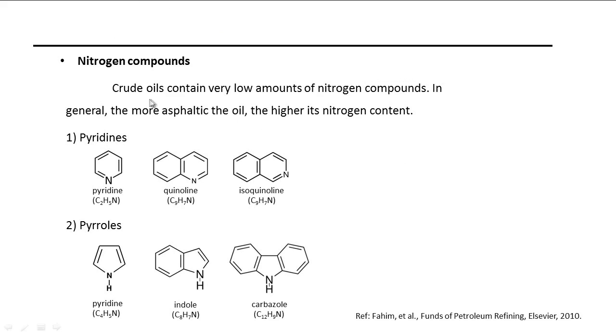In terms of nitrogen, the nitrogen compounds in the crude oil are not good for the engine as well, since they can cause gum formation, and the compounds of pyridines are quite strong in base, which can cause corrosion to the downstream process as well.